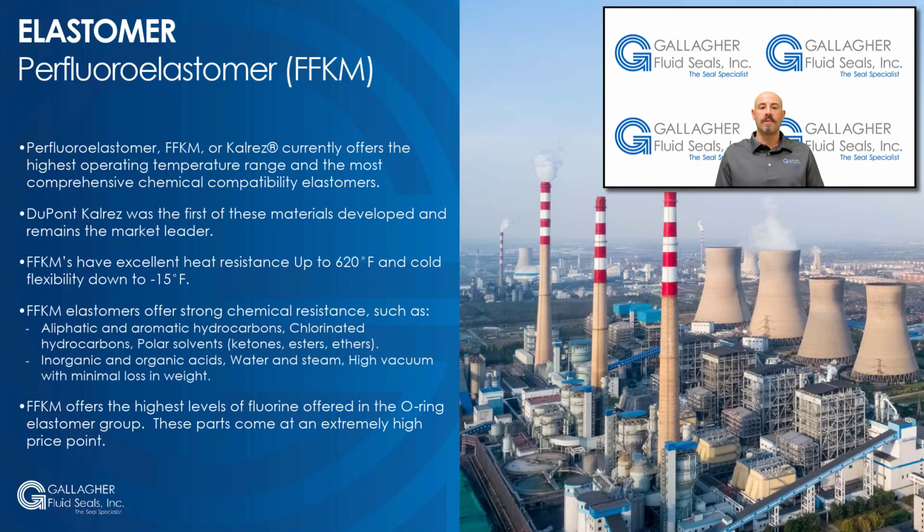Wide ranges of specific FFKM compounds have been developed to solve specific application challenges. These materials are used across a wide range of industries such as aerospace, semiconductor, oil and gas, and chemical processing. FFKMs have excellent heat resistance up to 620 degrees Fahrenheit and cold flexibility down to -15 degrees Fahrenheit. These numbers are compound specific and should be considered with your application needs.